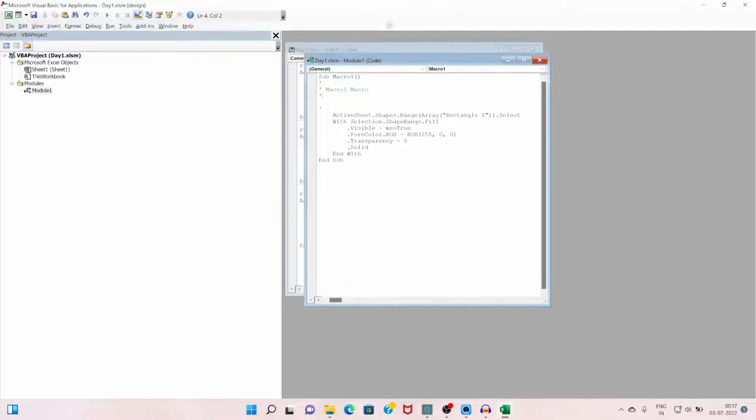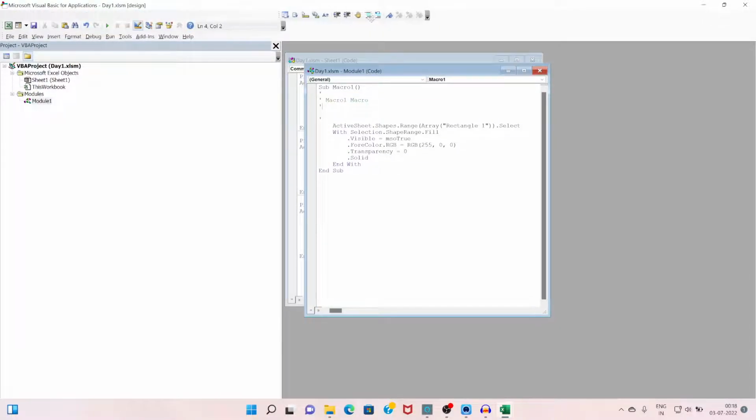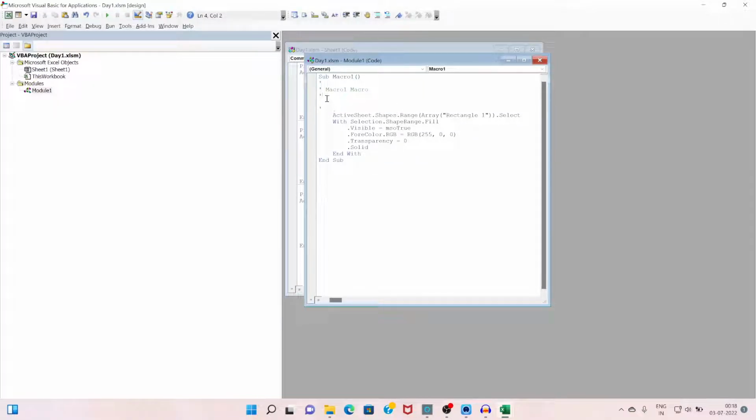From where does it come? Here, this will come by right clicking, edit button here. Okay, wherever you want to put just information, for information. Okay, unless and until you type an inverted comma here, it will not turn into a comment. If you want to remove it from comment, simply go to edit, uncomment, comment it, uncomment it, comment it, same as our STAAD file. So these are the editor files.